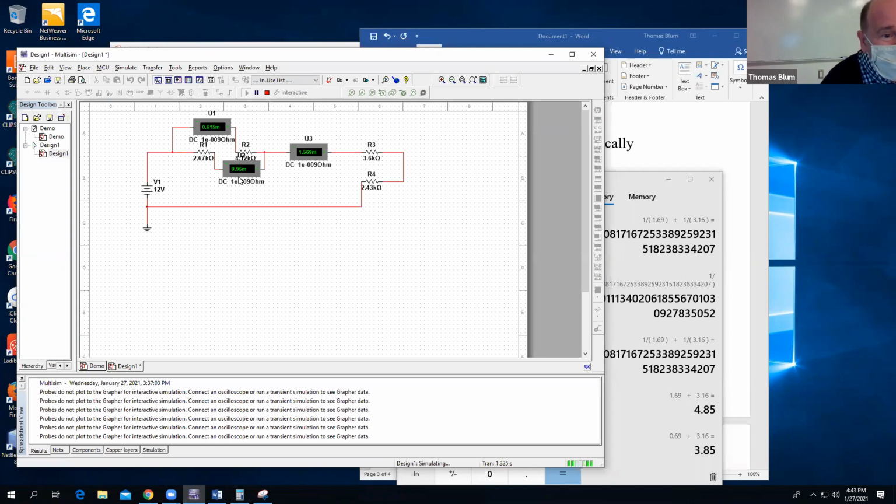And so what we see here, and this is something you'll have to do in lab 2, not quite with these values, but something like this. We see that these 2 currents, this current in the upper branch and this current in the lower branch, add up to the total current. So the current comes out, it splits up, some of it goes this way, some of it goes that way, and then it adds all together and carries on all the way through.